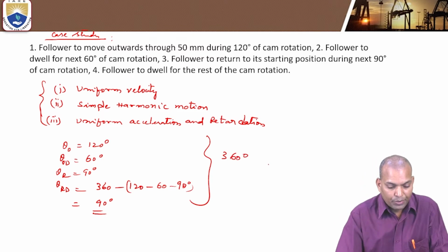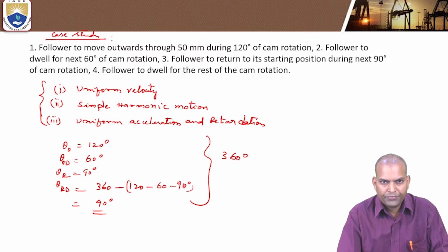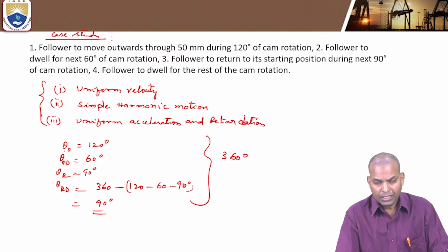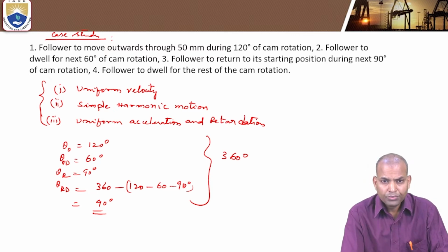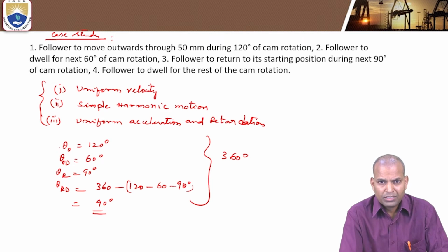Now here, what is the importance of the displacement diagram in the case of drawing the cam profiles? In drawing cam profiles, displacement diagrams are so important that without displacement diagrams, we can't draw the cam profiles. So displacement diagrams give the path of a follower for a particular angle of rotation of a cam.